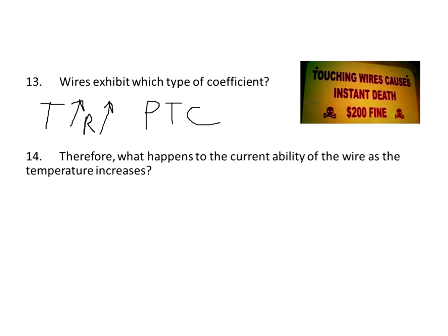I don't know if you've ever noticed this or not, or if you've ever experimented with those light bulbs in the lab room. Whenever you test those when they're cold with an ohmmeter, they read very, very low. But when you turn the light bulb on, under its operating conditions, when it's glowing, it has a very, very high resistance. So that would be a good example of metal. When it gets hot, the resistance goes up.